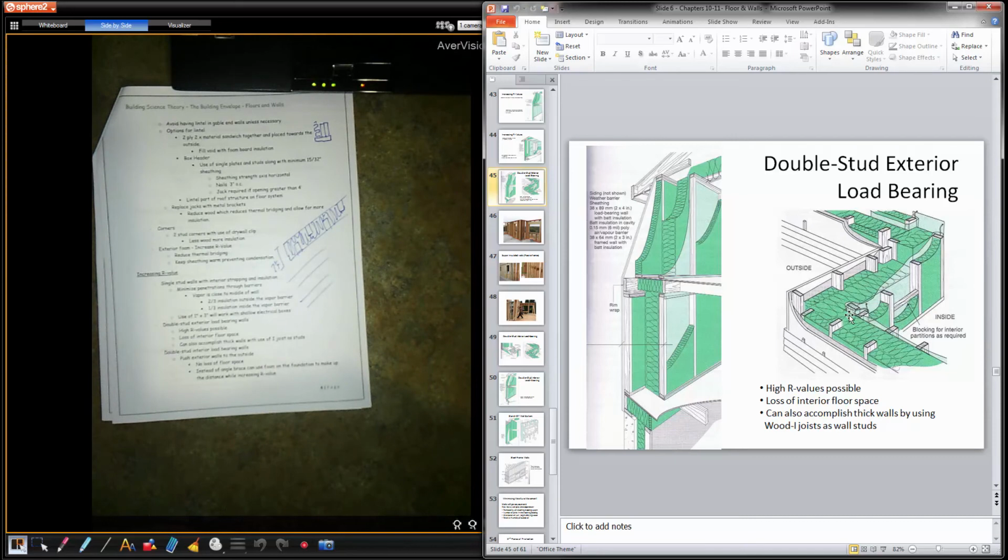Okay. So you can see thermal broken between two walls. The wall's very, very thick, so you're going to get a high R value here. Very high R value. Thermal broken throughout. Okay, so the key, you see where the poly is? The poly is closer to the inside. So there's more than 2/3 to the outside. Not as much on the inside.